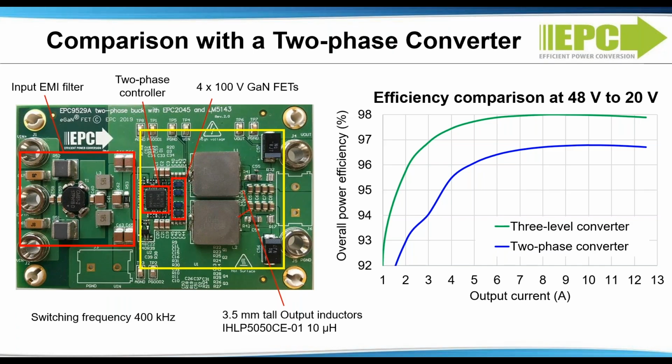What digital controller does EPC recommend, and why? All right, well, let me look that one up. We have the Microchip dsPIC33 that we use for most of our designs, and we do it because it's pretty low cost and low power consumption. So when we get to 98% efficiency, you've got to have very, very few milliwatts going through your microcontroller. It's in a 5x5 package, so it's also very small. So that's the one we use, but there are others. There are many good microcontrollers.